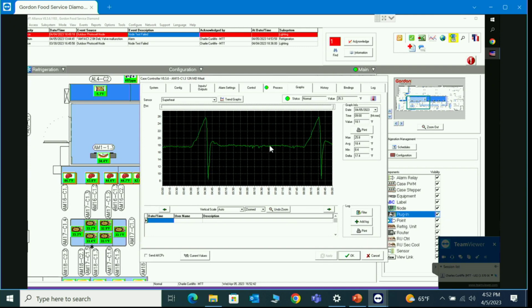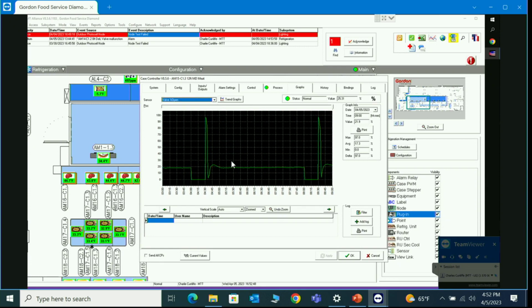All right. So let's just see what the valve position has been. Again, stable. Why have that valve hunting all over the place? It's fixed right there, it's perfect. The superheat is good. The temperature is good. Why have it all over the place? So now that's a zoomed in view. I know I'm going fast, guys. I apologize. Let me look for 4 days here.